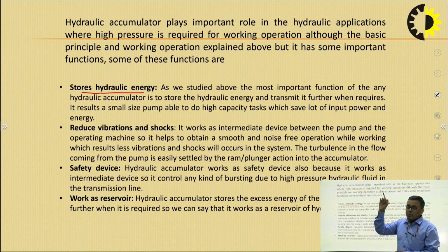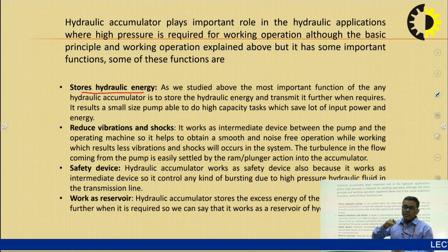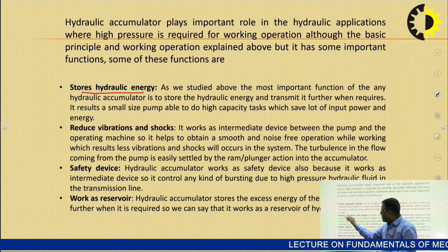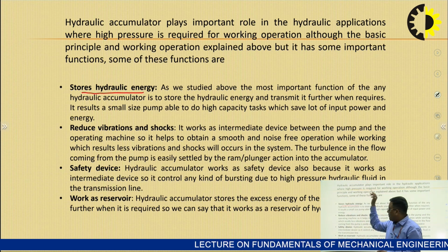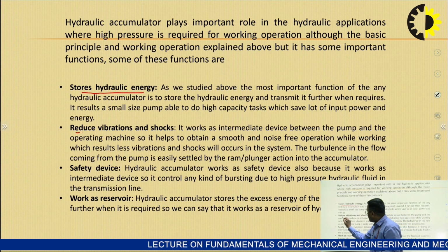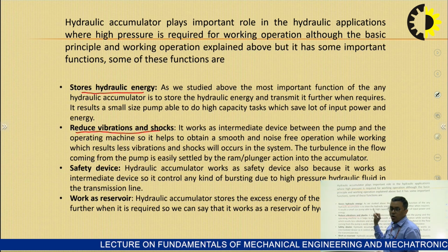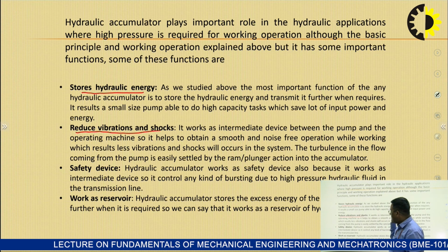If the requirement is not getting fulfilled by the pump, then what will happen to the application? The crane or lift will feel certain jerks or vibrations. So for reducing the vibrations and the shocks, we put the hydraulic accumulator, so that the resultant vibrations and shocks will be lesser.